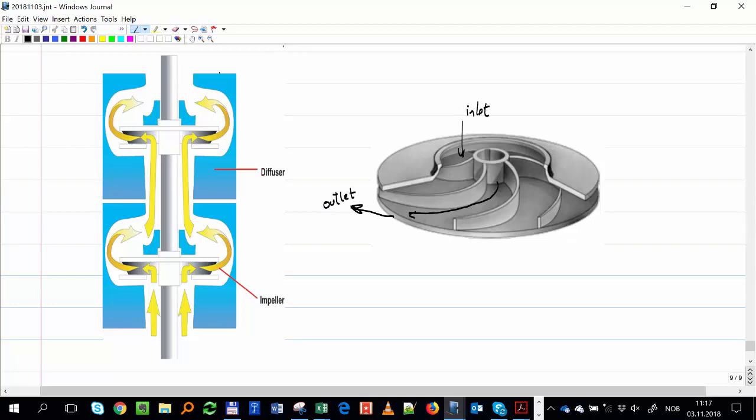And you know, in a pump, you have two things. You have the rotor, which gives energy to the fluid by accelerating it. In the rotor, you have acceleration, increased transfer of velocity to the fluid. And then you have diffusion, the pressure recovery. You have two processes: acceleration of the fluid, basically increasing V, and then the second process, which is pressure recovery.